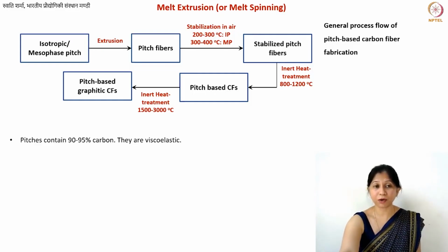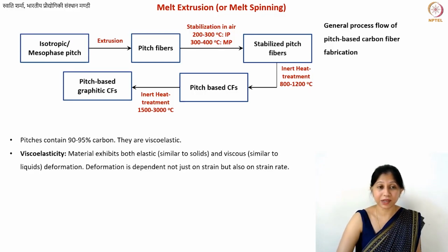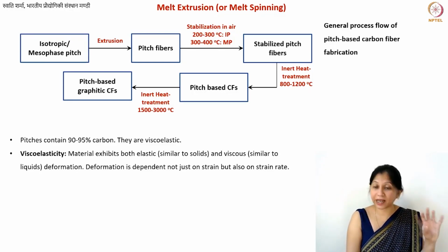Some important things about pitch is that most of the pitches have their purity between 90 and 95%. A little bit higher is also possible, but most of them have, let's say, 95% purity. They have this special property known as viscoelasticity. As I mentioned before, we are going to dedicate some time on viscoelasticity, but briefly, the definition of what is viscoelasticity. As the name itself suggests, this material has both viscosity and elasticity.